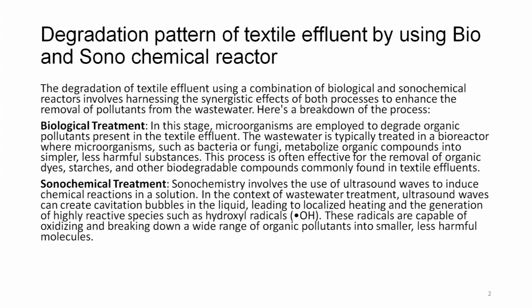So, it is now very clear that biological treatment requires the role of microorganisms, and the enzymes secreted by them, that is by bacteria and fungi, can metabolize the organic compounds present in the effluent into simpler and less harmful substances. Whereas, in the sonochemical reactor, the ultrasound waves create cavitational bubbles in the liquid, leading to production of hydroxyl radicals. As I had told earlier also, these hydroxyl radicals are extremely reactive and can break down the organic pollutants to smaller and simpler, less harmful substances.